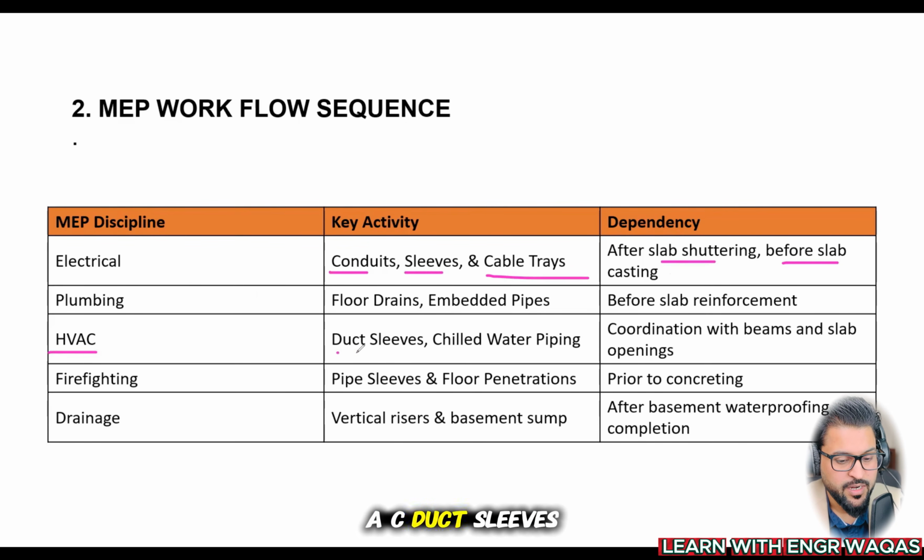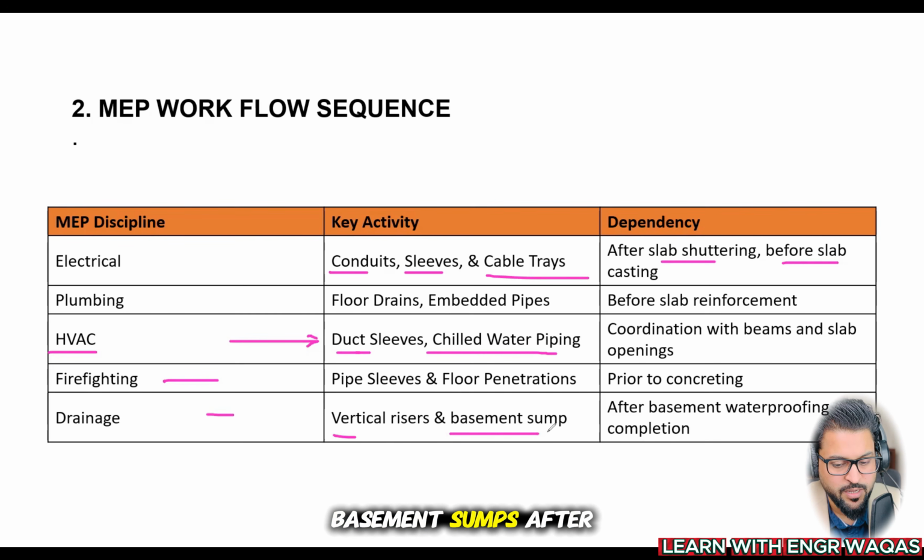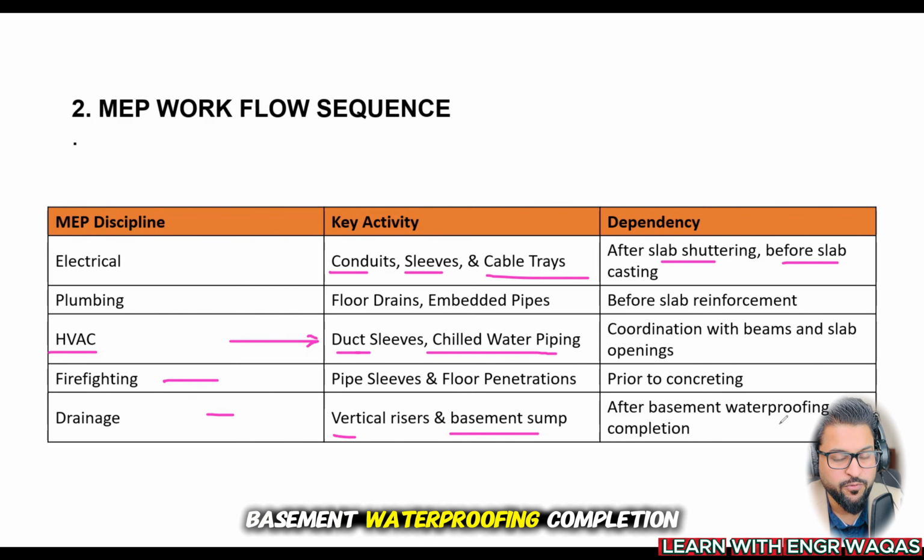HVAC, duct sleeves, chilled water piping. These are the activities that come under HVAC, and these activities should be linked or coordinated with beams and slab openings, right? Firefighting, these pipe sleeves and floor penetrations prior to concreting. Drainage, vertical risers, basement sumps after basement waterproofing completion.